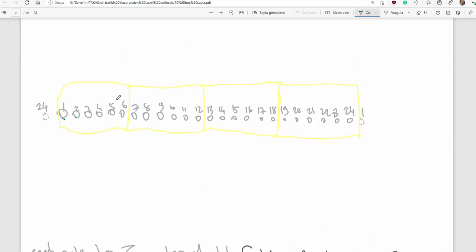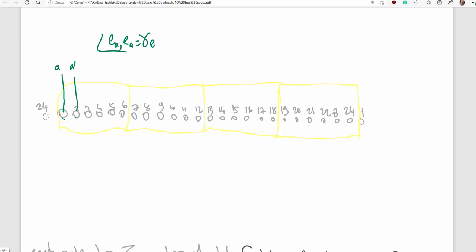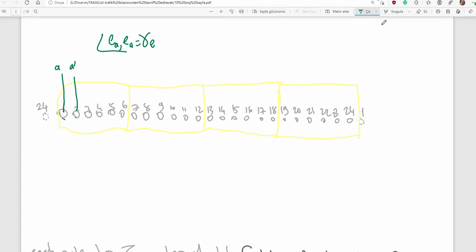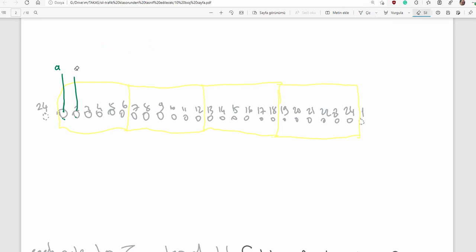I mean, assume that here's a conductor, here's another, let's say A and A prime, and the phase difference between A and A prime is equal to gamma electrical. That is the phase displacement between adjacent slots in electrical manner.